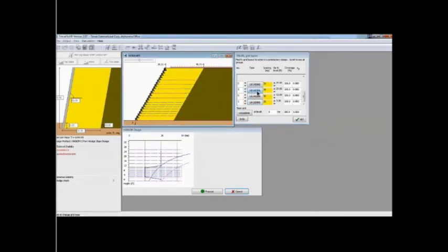We could also potentially make this geogrid weaker, so let's click through the names of the products, and now UX 1100 is green, and you can see that the spacing is not okay because at this elevation here, our UX 1100 should be no more than roughly 30-inch spacing, but we have it at 36. So we'll add a layer of geogrid below, add another one in the third, and let's add a layer at 18-inch spacing at the top, just so we have some more geogrid towards the top of the wall. There we go. And now we can click on Go Proceed.